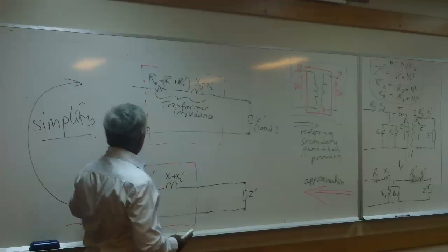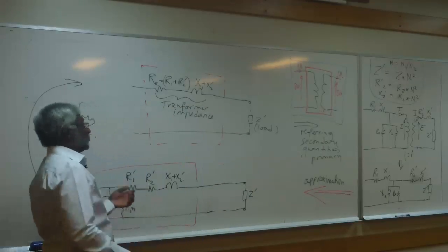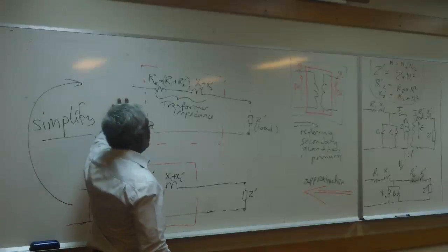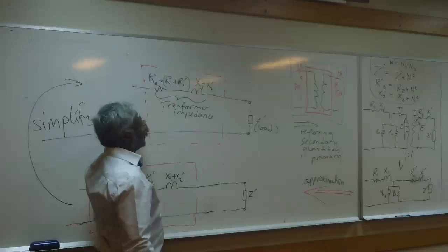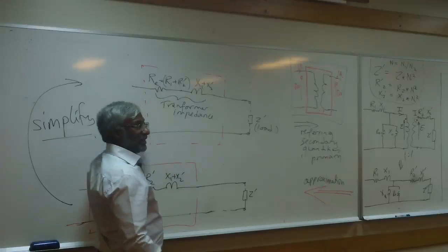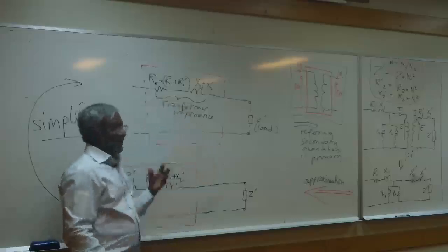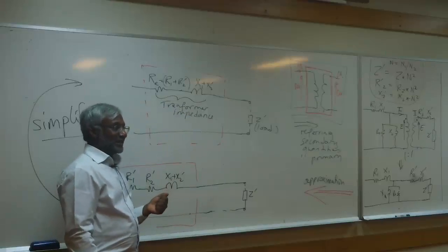Okay, so be careful. You do your short circuit test. You normally do a short circuit test at the rated current. So you would have a variac here. You turn it up until rated current flows. Then you measure the voltage, and the voltage divided by the rated current would give you that impedance. And that's what we call the transformer impedance.